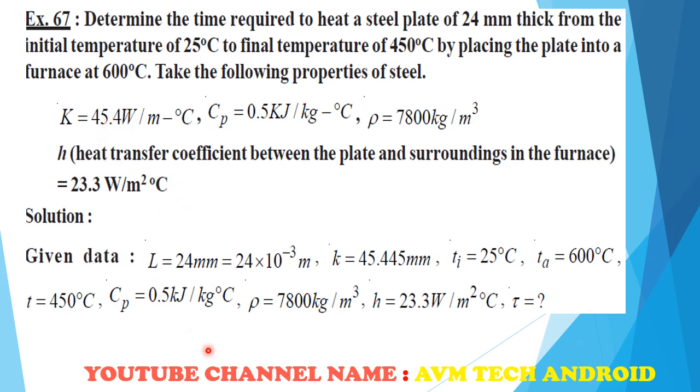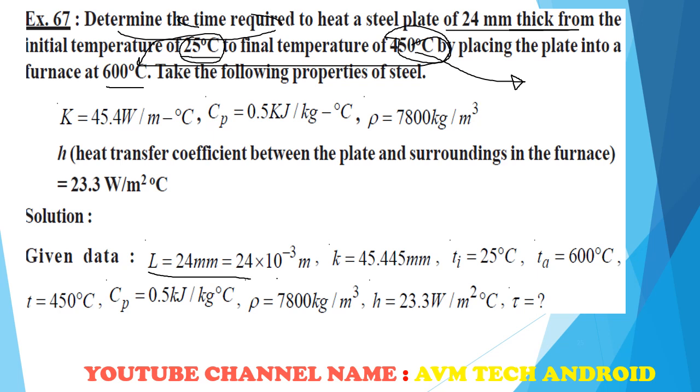So friend, this is again a case where the initial temperature of the plate is 25, the furnace temperature is 600. We have to put this plate into the furnace and achieve the temperature 450. The plate dimensions are given and we have to find out the time required for this temperature to be achieved. You can see the thickness is given in millimeter, we have to convert into meter.